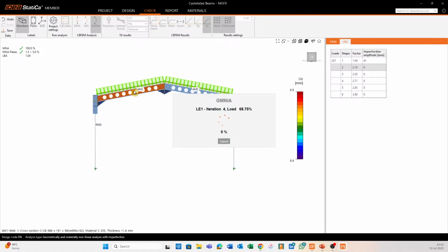Now, just importantly, while we're waiting for this to finish, one of the reasons why I checked whether or not the flanges and the webs are class 4 is that Member has not been verified for class 4 checks. Now, a class 4 element is an element where local buckling will happen, or rather where the element would fail in local buckling prior to reaching its yield stress.